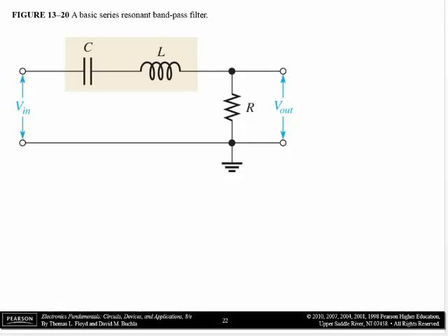So why have we studied this particular circuit, and what's it good for? That's probably the ultimate thing. We figured out that an RC circuit has some filtering properties, and so does an RL circuit. But what about an RLC circuit? What is it good for? It depends again on where you take the output from. Remember when we had an RC circuit, if you took the output from the capacitor, it was a low pass filter, but if you took the output voltage from across the resistor, it was a high pass filter.